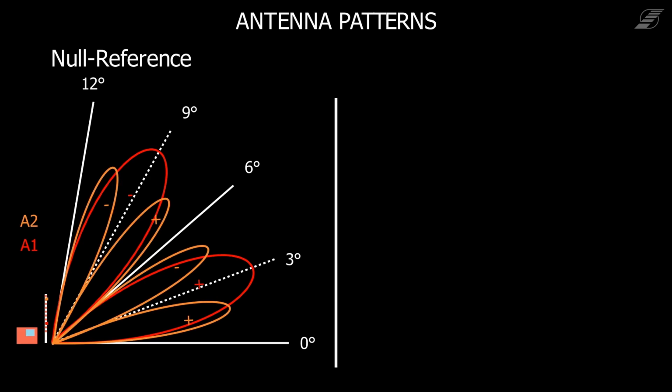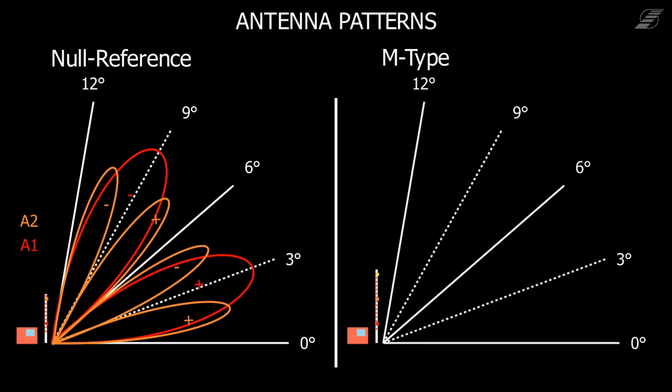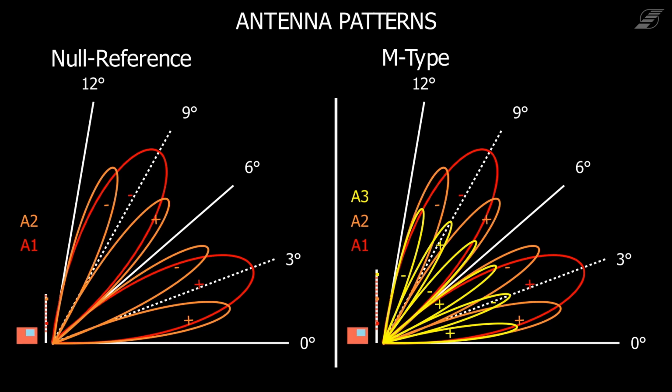The M-type glide path has an additional antenna at about 12 meters height. It radiates the narrowest lobes. The lobes are alternately in phase and anti-phase to each other, which is shown here as plus and minus. These individual lobes can now be overlaid to create the CSB, SBO, and clearance lobes for the M-type glide path as shown in the following.